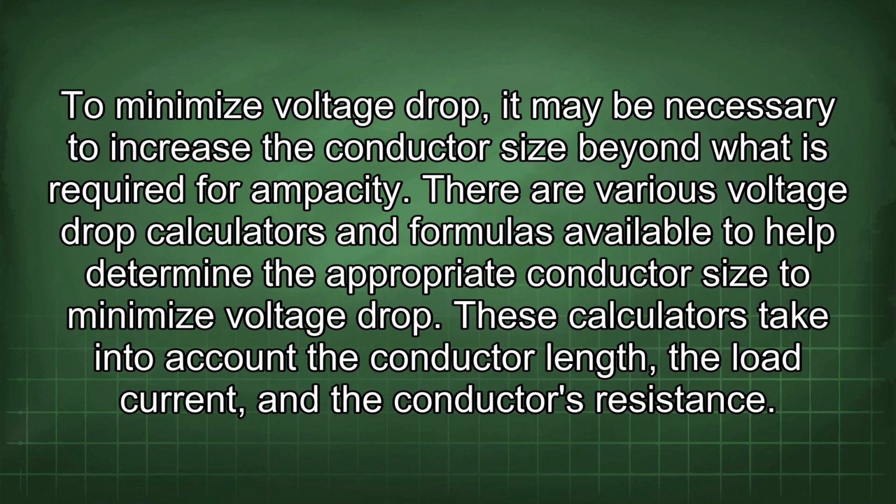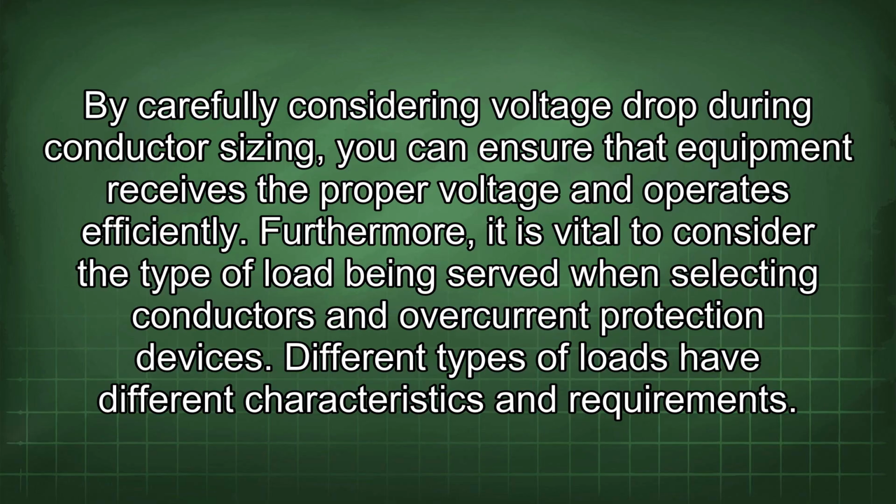To minimize voltage drop, it may be necessary to increase the conductor size beyond what is required for ampacity. There are various voltage drop calculators and formulas available to help determine the appropriate conductor size to minimize voltage drop. These calculators take into account the conductor length, the load current, and the conductor's resistance. By carefully considering voltage drop during conductor sizing, you can ensure that equipment receives the proper voltage and operates efficiently.